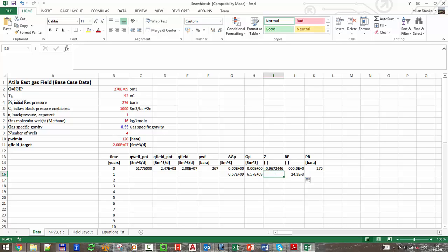That we need to assume a pressure, get the z, then calculate the z, again use the pressure. To make your life easy, I'm going to say the pressure change is not going to be much, I assume, from year to year. So the z shouldn't change much from year to year. So for that z, I will use the pressure from the previous year to avoid this implicit calculation. The implicit calculation, probably you're going to get it in the exercise. But here in class, I take the pressure from the previous year to calculate the current pressure.